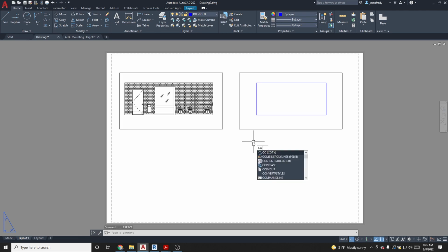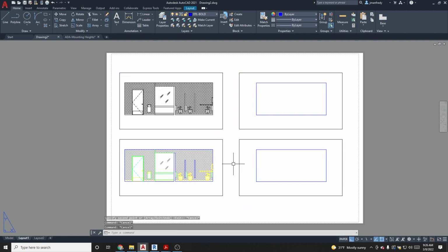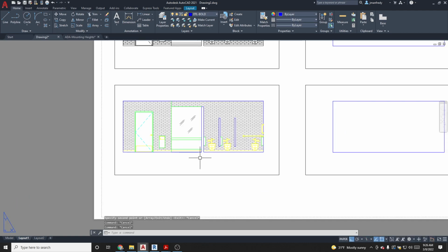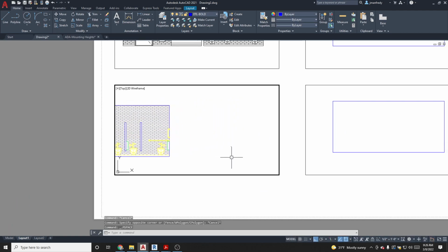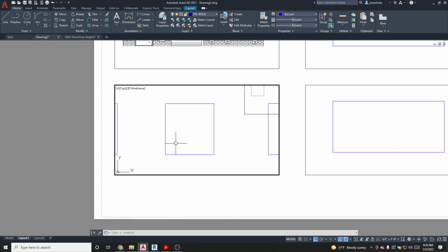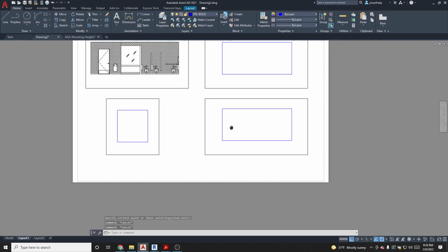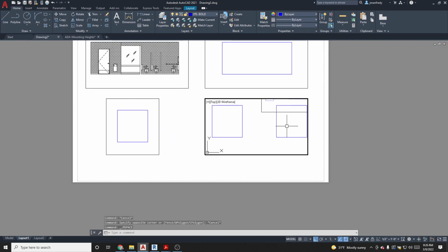I can copy both of these M views and then again adjust this. Double click inside and slide it over. That's elevation number 2. That's elevation number 3. Again, you don't want to see extra things sitting out here, so make sure you adjust this box by moving it closer and just focus on what you want to see in the elevations. Like for example, just that much. Double click here, and you're going to show the last one, which is this one here.